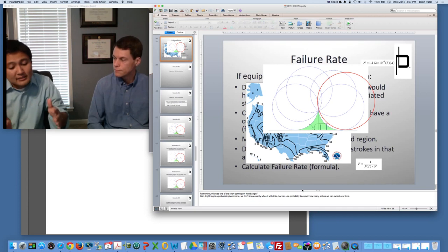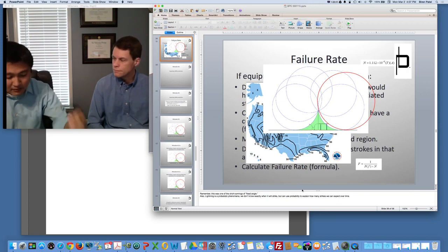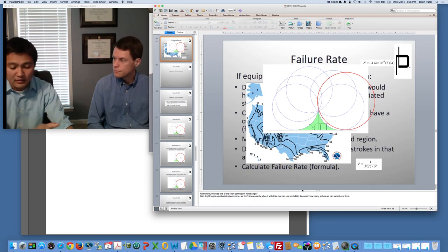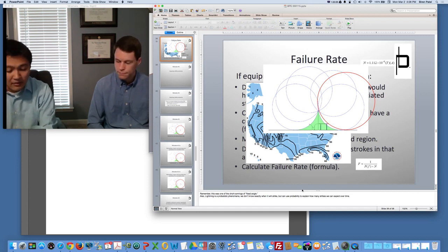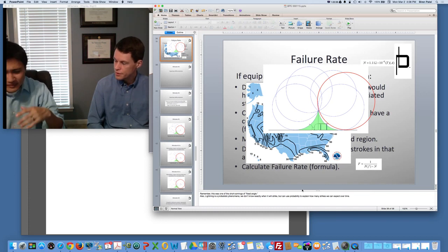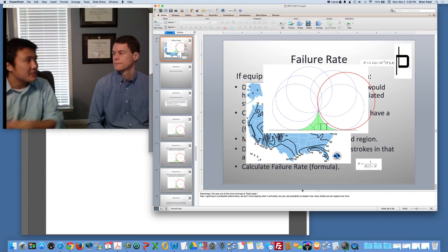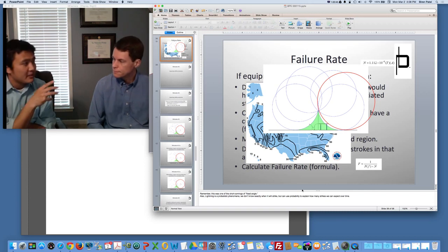Generally speaking, I like to say, define at least 2, if not 3 categories of priority substations. Priority 1, our top priority substations, cannot go down. We need to have 400 or 500 years between failures. And then you may have priority 2 and then priority 3, priority 3 being the lowest priority. If these things go down, there's a lot of backup. It's not going to cost us a lot. We'll accept 1 failure every 100 years.